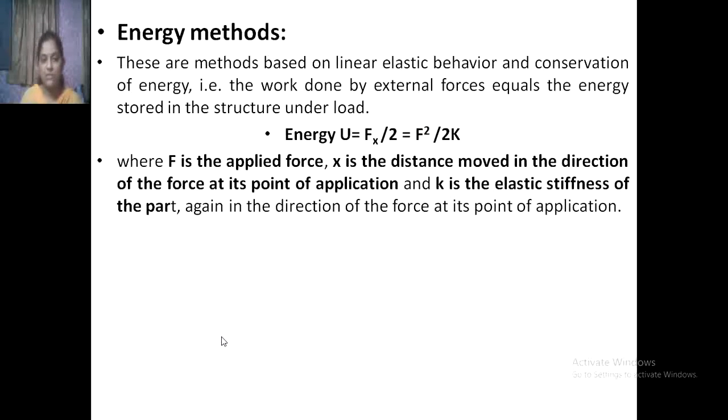These are methods based on linear elastic behavior and conservation of energy. That is, work done by external forces equals the energy stored in the structure under load, that is energy Q is equal to Fx divided by 2, which is Kx squared by 2. Where F is the applied force, x is the distance moved in the direction of the force at its point of application, and K is the elastic stiffness of the part.